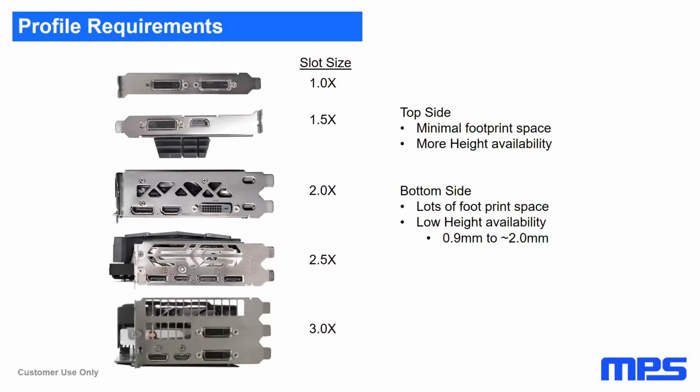Traditional power solutions are kind of constrained; they have one footprint, especially for discrete. The inductor can be the most difficult thing to place, because a lot of customers will try to put the switcher on the back and the inductor on the top, since the inductor is usually going to be more than the 2 millimeter requirement, especially for the core.